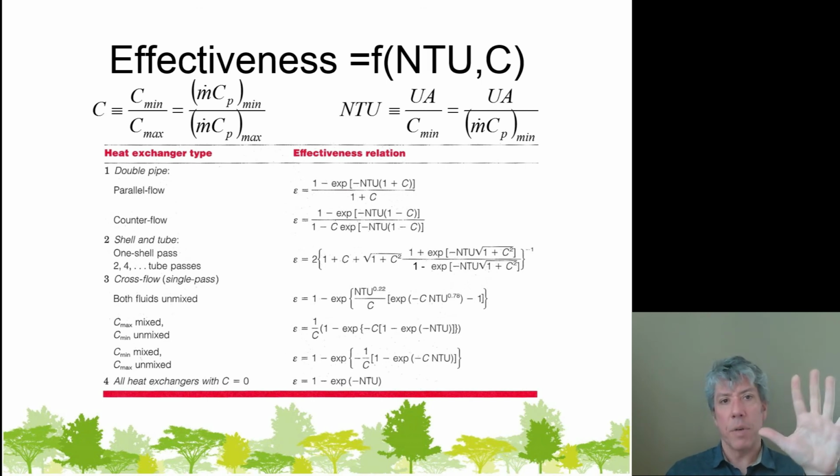Now we've got 5 different C's running around. We've got the heat capacity on the cold side, we've got the heat capacity on the hot side, we've got the minimum capacity rate, which combines the heat capacity with the mass flow rate. We've got the capacity rate on the other side, right? One of them's maximum and one of them's minimum. You could argue we've got 7 C's running around. And now we're using C again to represent the ratio of the two capacity rates, where we always take C minimum over C maximum. Sorry, I didn't make up the symbols, but fortunately, this capacity rate is one of the easier things to get at. Coming up with a capacity rate really is not that hard. You just have to keep all the C's straight, that's all.